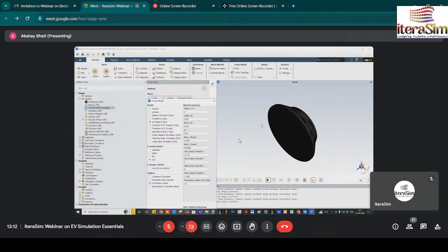You can blindly follow that k-epsilon model, any wall function or anything you can give. But if you know that your model may be somewhere in that one turbulent and that one laminar zone, it is better to use k-omega, because near the solid surface, near the boundary layer, because first k-epsilon was developed. But in k-epsilon some researchers found that it does not accurately capture the boundary layer effect, the velocity gradient near the solid surface, because with the no-slip condition there would be some velocity gradient near the solid surface.